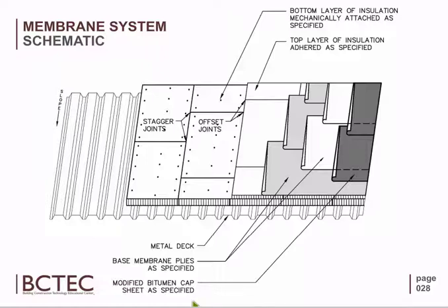If you pop that ceiling tile out, see what kind of decking it is, which way it's going, that'll play a lot in your findings. So what you want to do is pop that tile, look at the deck. If it's concrete decking, your water can travel 30, 40, 50 feet before it finds a weak spot.